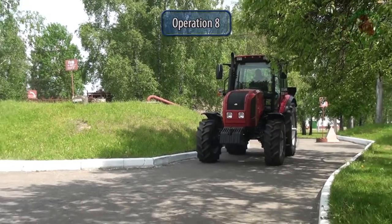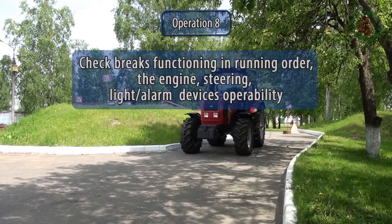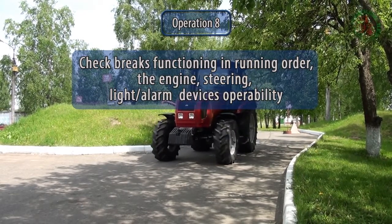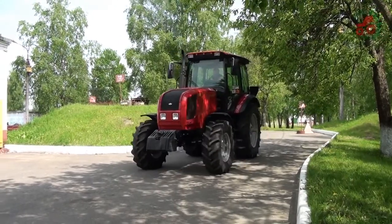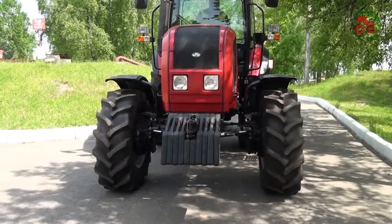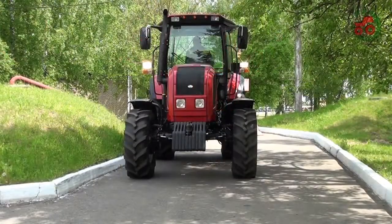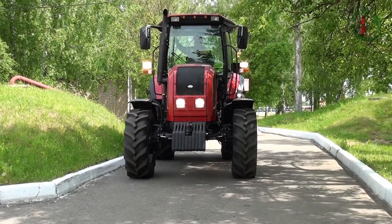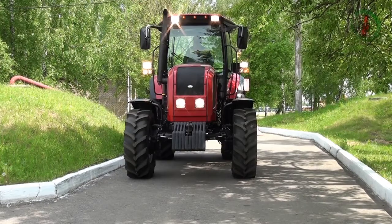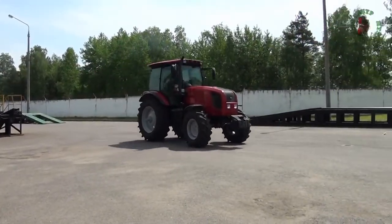Operation 8. Check brakes functioning in running order, and the engine, steering, light alarm devices operability. The engine shall work steadily in all modes. Control elements, light warning, and acoustic alarm devices shall be properly operated. Simultaneous engagement of the right and left service brake shall be ensured.